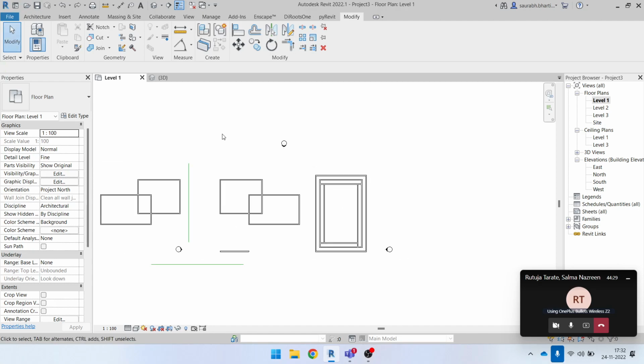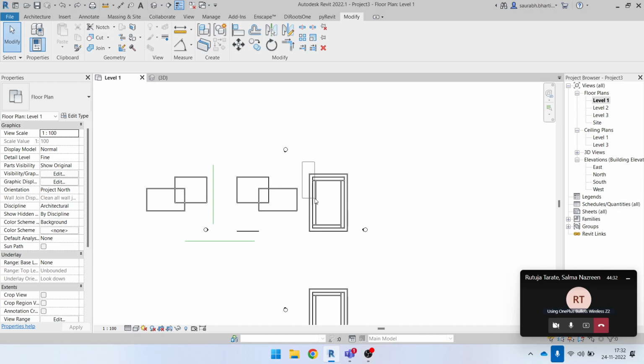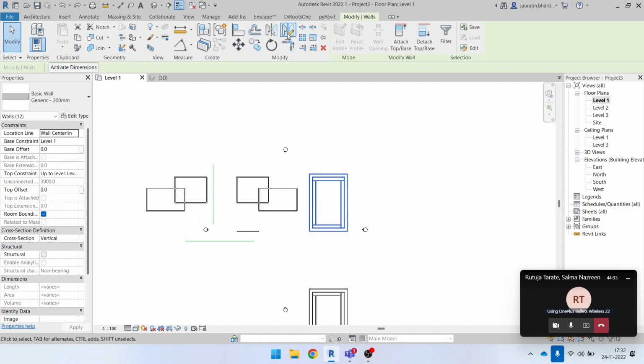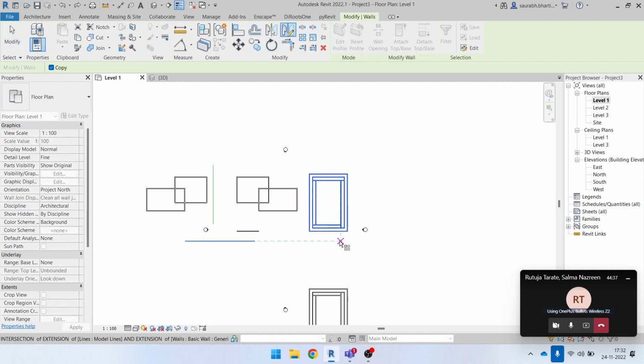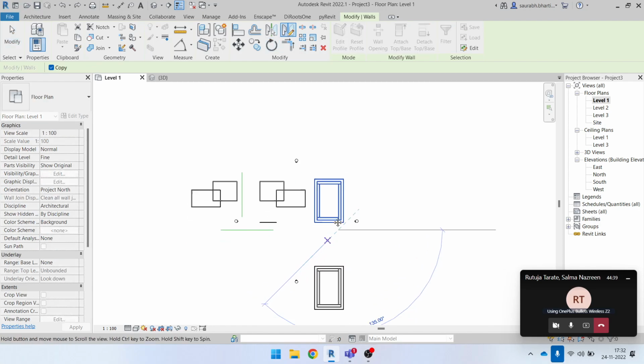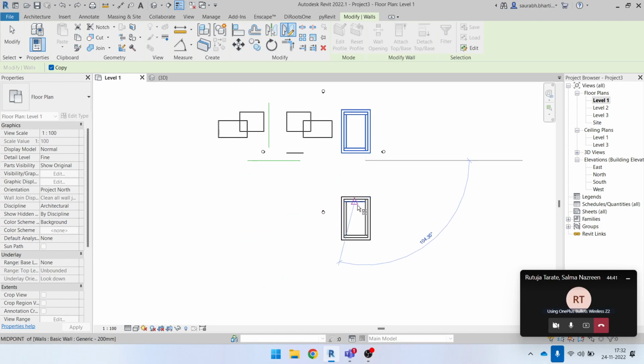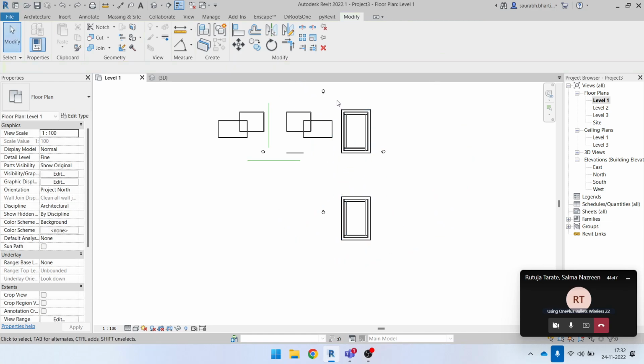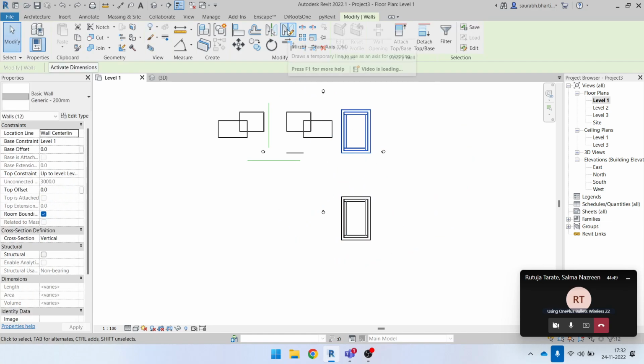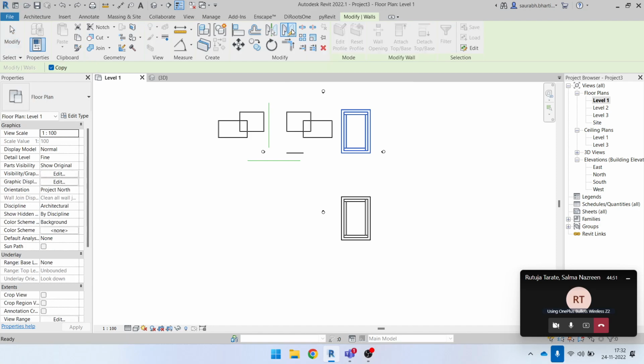Okay, and now I want to mirror the same thing on an angle. So I will go for draw axis. Here I'm creating this angle, and you can get whatever angle you want as I move my mouse. First I select the object, then click on this draw mirror option.